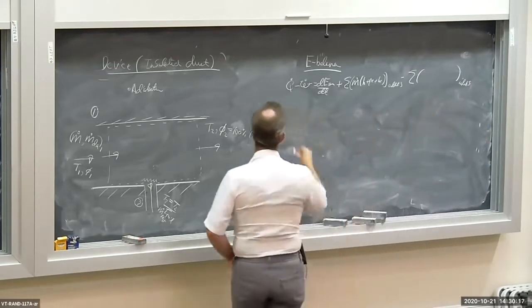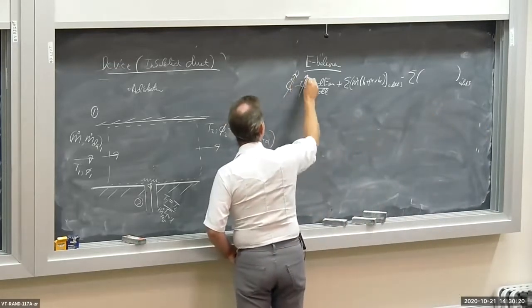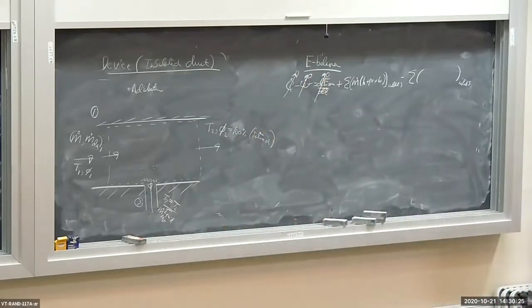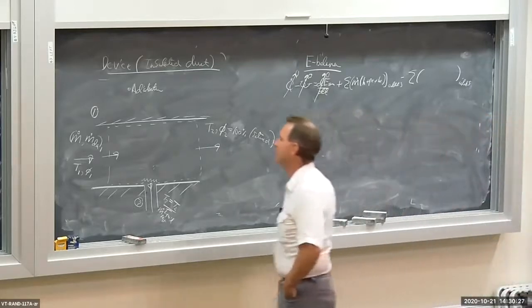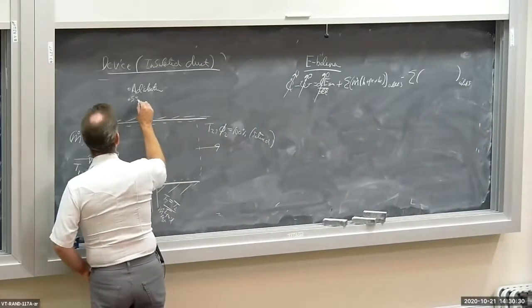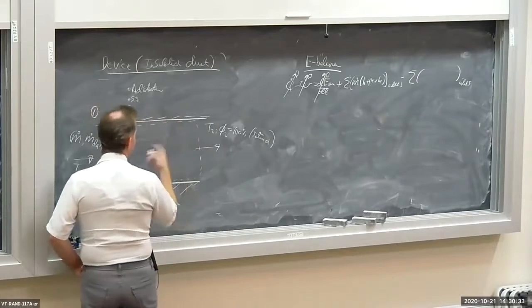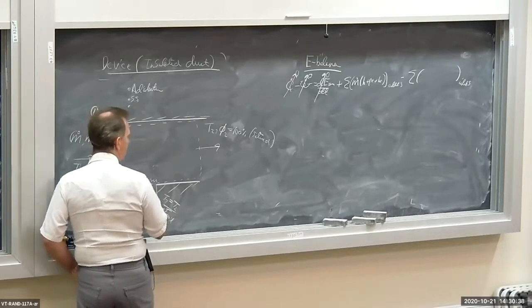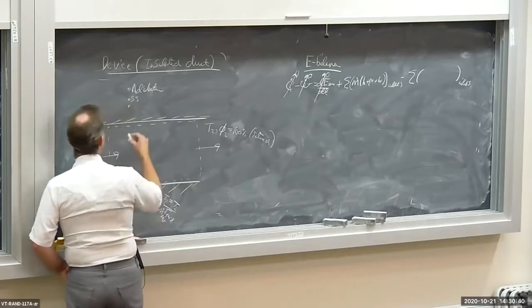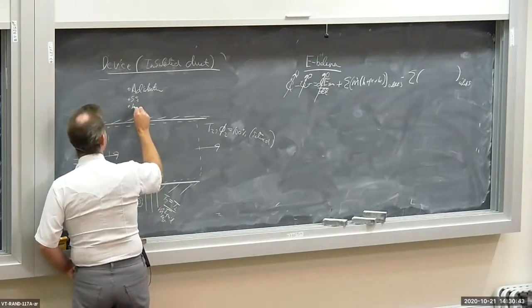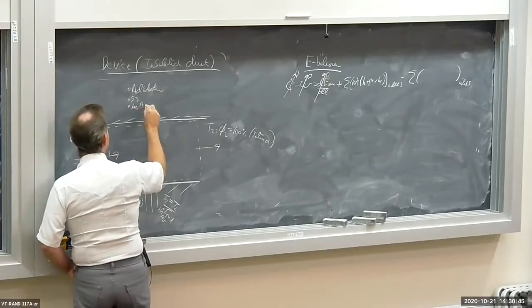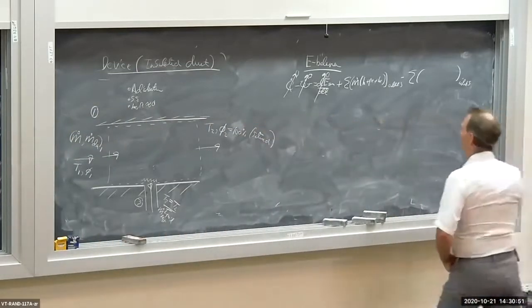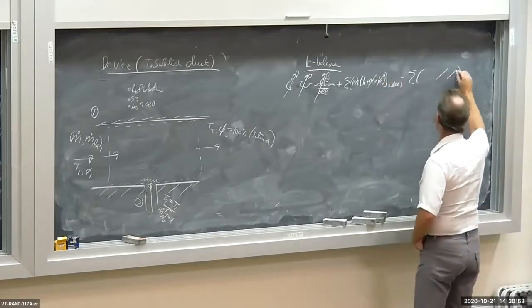No heat transfer, no work. We're going to assume it's steady state as well. This is clearly a steady state problem, okay? So it's adiabatic, steady state. I'm also going to neglect changes in kinetic and potential energy of the moist air flowing in and out of the duct, and the kinetic energy of the H2O being pumped in as well. So the specific kinetic energy and specific potential energies at all inlets and outlets approximately equal to 0. So I can get rid of these potential and kinetic energy terms, okay?